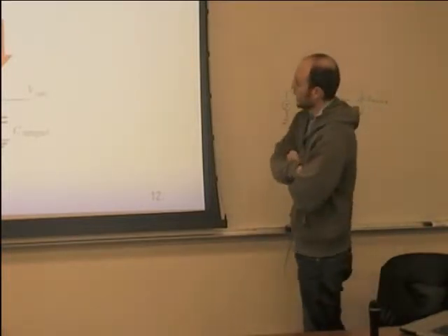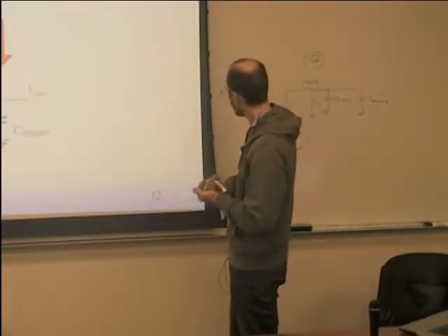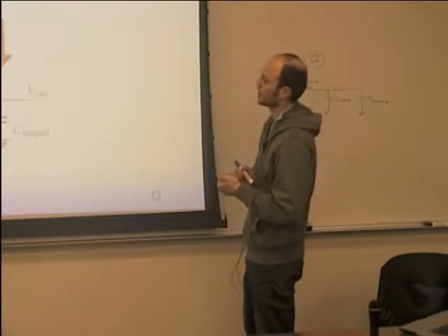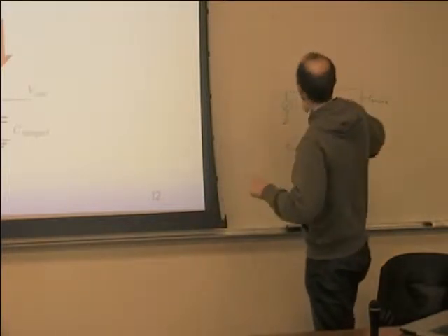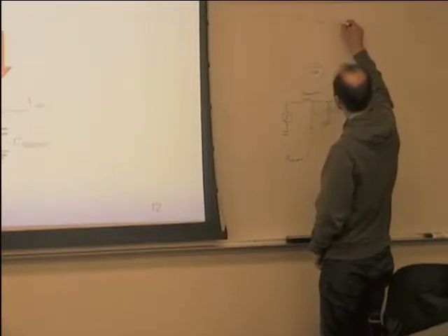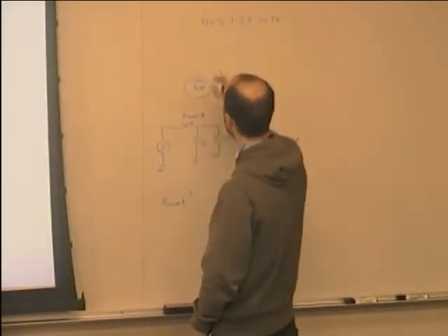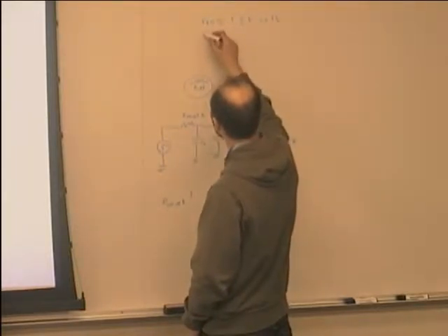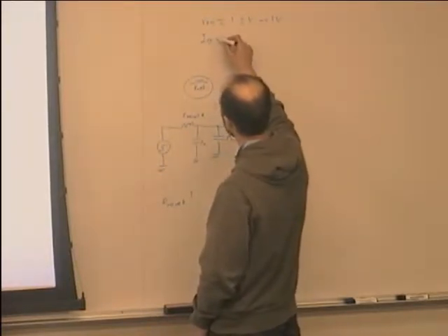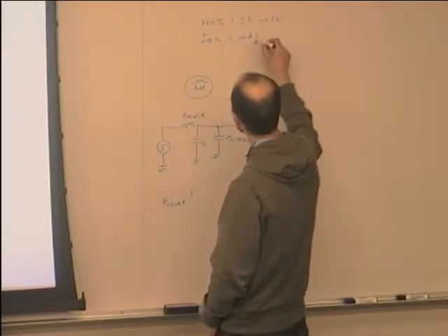10 ohms, yeah. So actually, 10 ohms would be a very big transistor. The one thing that you can remember as an order of magnitude is that VDD is about 1.2 or 1 volt, and the current that the transistor puts out is of the order of 1 to a few milliamp per micron.